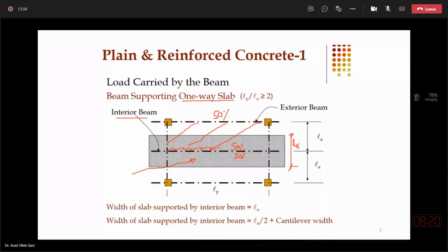So first thing is how to get this pressure. I mentioned in one of my lectures that if you are provided with the thickness of the slab, actually the thickness of the slab will be your first step when you design the slab. So deciding the thickness will be your first target. When we discuss design of slabs, you will first fix the slab thickness.